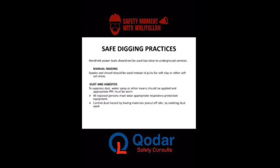Now, for safe digging, it is advisable that handheld power tools, such as a jackhammer or a drilling machine, should not be used close to underground services. Rather, a shovel or a spade should be used instead.